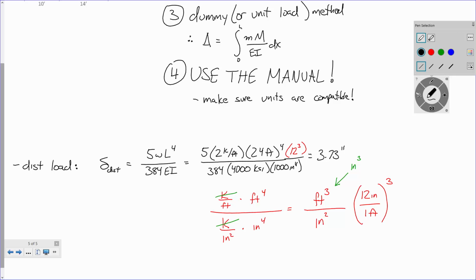What do you think the answer to the problem is? It's probably C, right? It can't be B. It obviously can't be A or B, and D just doesn't sit right. Well, we can keep going if you want, but 2 kips per foot over 24, that's 48 kips. Okay, 48 kips caused that much deflection. How is 20 kips going to cause 9 inches? Doesn't make any sense, does it? But we already know what the answer is, right?